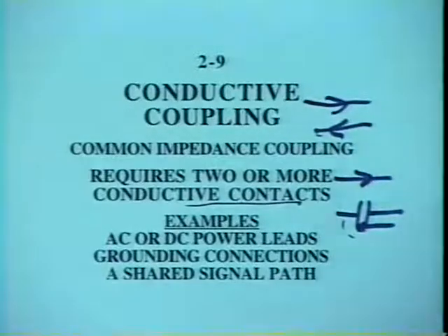What are the 2 wires that we typically have to worry about that are going to bring in or out this unwanted conductive coupling? Well, DC power is the #1 pair of wires to be concerned about. All electronic circuits need some kind of DC power to operate off of. Those 2 wires that bring the DC current in and out of our circuit, those same 2 wires can bring in the unintentional conductive noise. A lot of times we're running things off of AC power. That's how we get the DC power. So it may all start with unwanted conductive noise coming in on the 2-conductor or 3 or 4-conductor AC line. So power connections, particularly DC, but power connections are our prime concern for unwanted conductive noise.